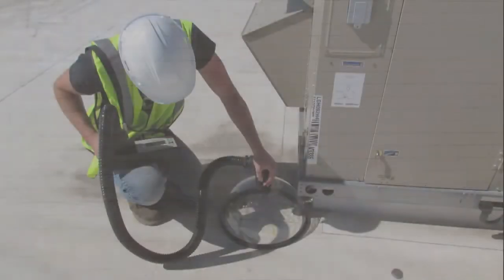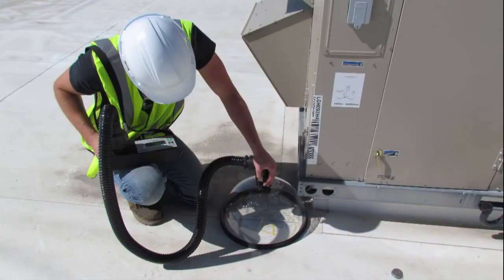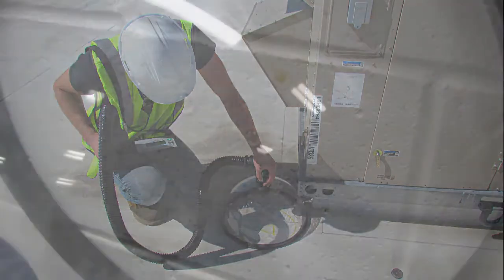require that building envelopes be designed to control air leakage. The IECC also designates paints on concrete block as an air barrier. In order to comply with the mandate to restrict air leakage, a variety of materials are used during construction. Testing is also performed to confirm that leakage doesn't occur. The bubbles here show a leak.